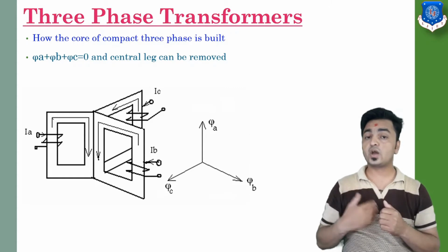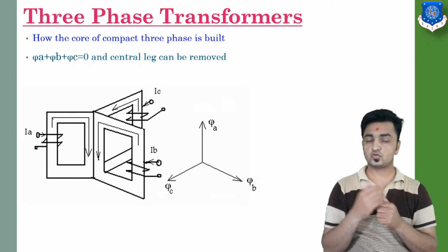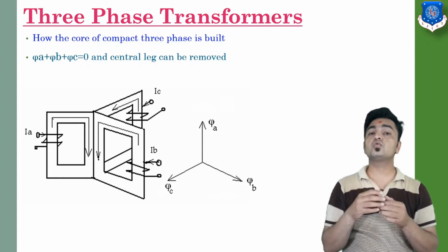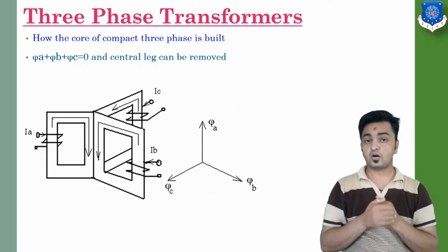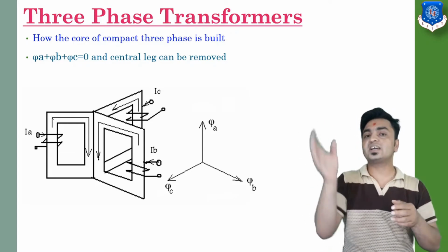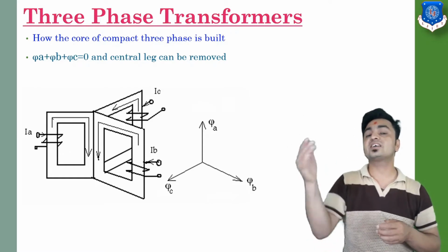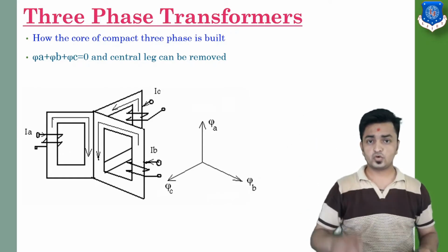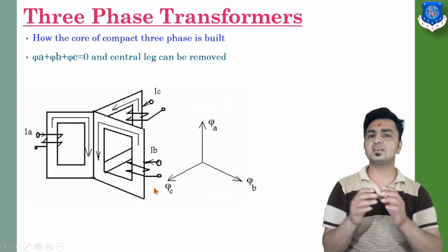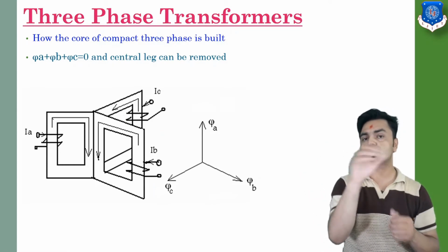In the same way, we are going to design a three-phase transformer. We can use that type of three banks, with windings wound on the vertical sections, meaning the limbs. This diagram represents these three sections.